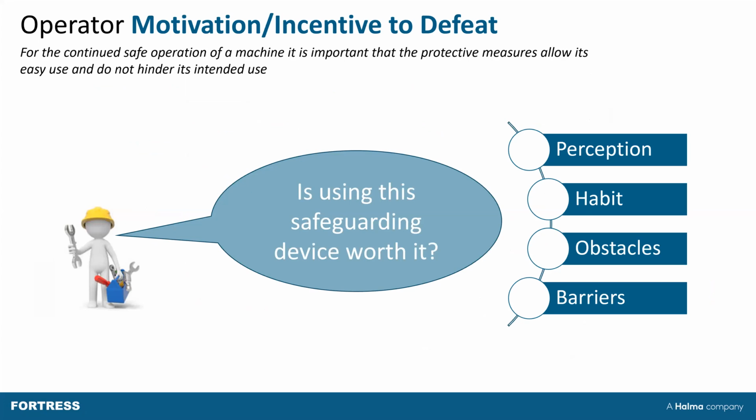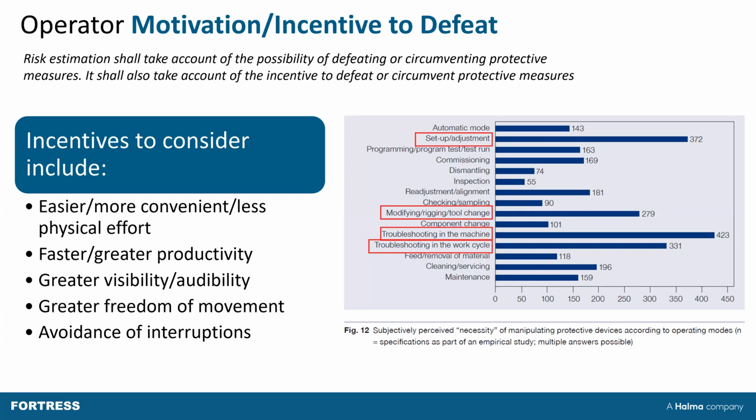Yeah, thanks, Eve. It's become a topic that has kind of dominated my working life at the moment. A study back in, it was probably about 2006, 2007, carried out in Germany by independent bodies, found that 70% of interlocks were defeated on site. And as a result of that, we've seen an amendment to 14119, then a rewrite of 14119, and 14119 is again being rewritten. That's the interlocking standard. And I think it's going to have about 10 pages devoted to motivation to defeat.